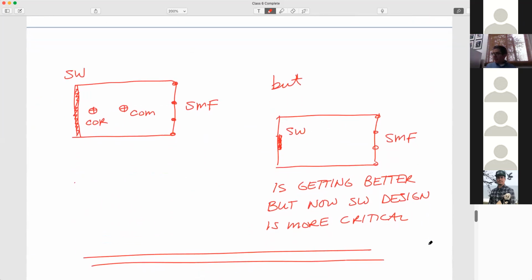All right. So here we'd be back to a picture on the left here. We've got a shear wall on one side and a steel moment frame on the other side. So we have a very big stiffness incompatibility. The shear wall is much more stiff than the moment frame. So there's the center of rigidity, right? The stiffness center. And then there would be the center of mass. So this creates the torsional response.